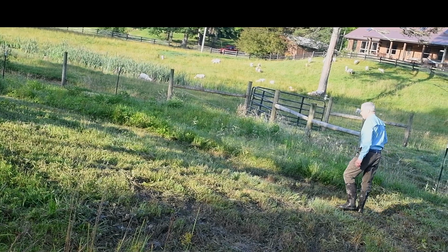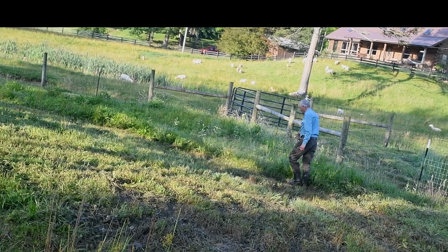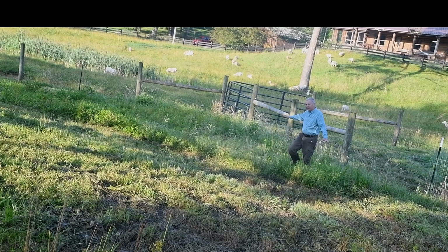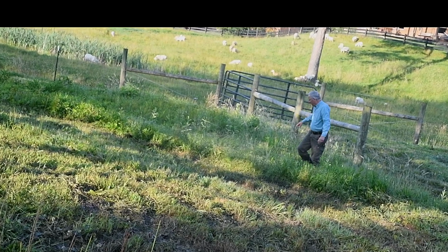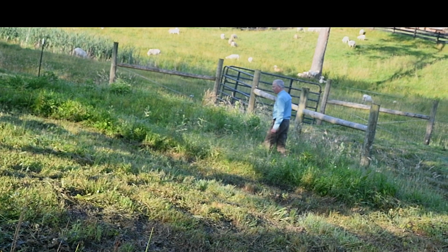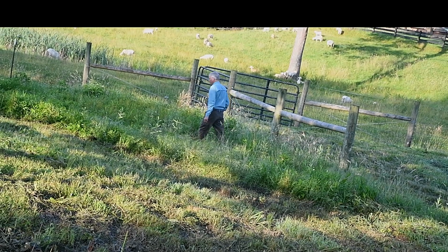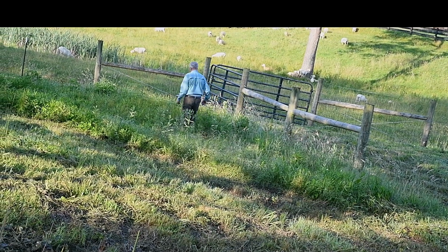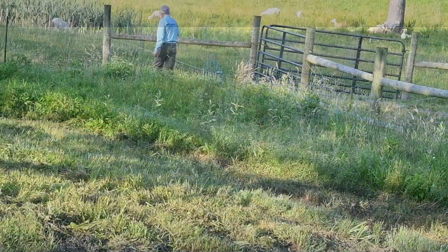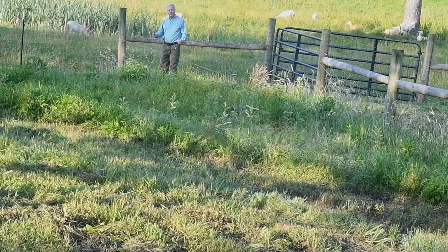I'm going to continue walking the spillway. I'm following the flow. I have rubber boots on because the ground is wet. And right here, the water starts spreading out and forms this large wet meadow. And I'm going to keep going until the spillway leaves my property and see if there are any head cuts where the spillway drops into a ditch. So I'm going to keep walking the spillway. A wonderful diversity of plants. And here the water spreads out, seeps underneath the road. There are no head cuts.